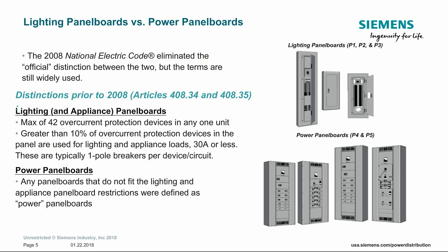So one kind of interesting note to mention is that residential load centers are actually considered lighting panels. So the only main difference is that residential lighting panels incorporate plug-on breakers, while commercial lighting panel boards typically include bolt-on breakers. Also, the load centers in your home are typically made to be smaller so that they actually fit between the studs in your house.